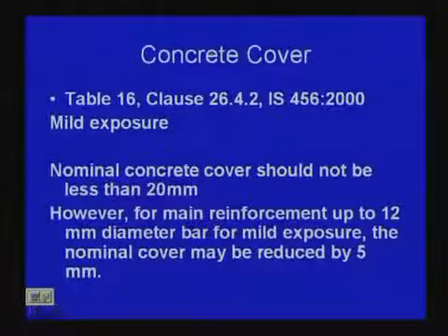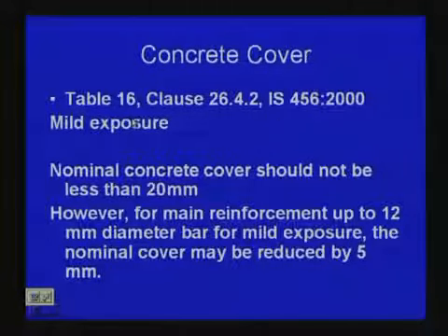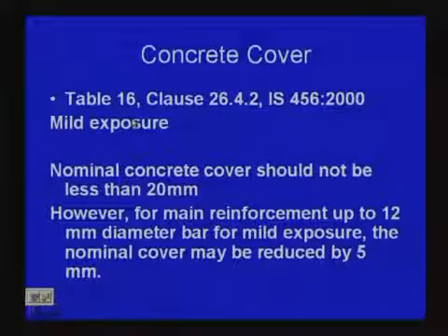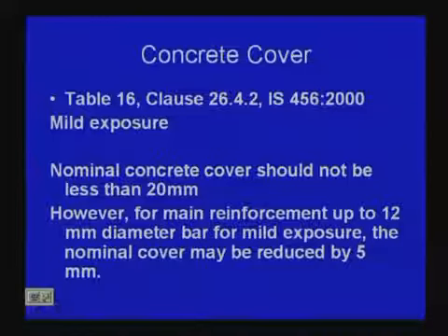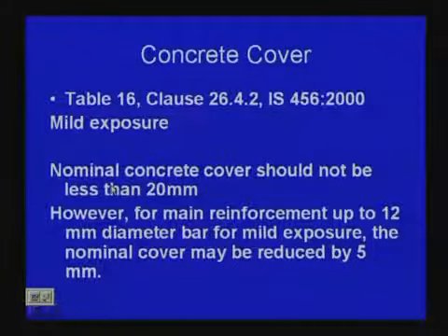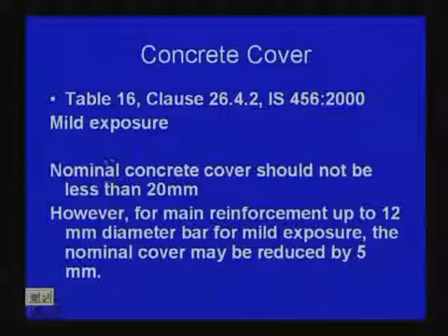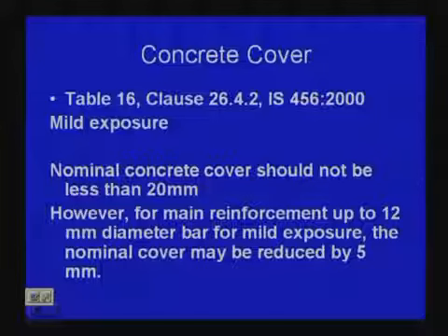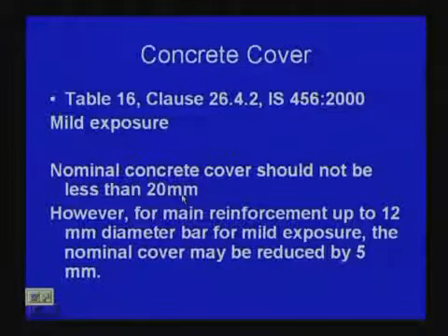What about the concrete cover? You will find that in table 16. We have already used a clear cover of 25 millimeter for beam. So, you will find in table 16, clause 26.4.2 of IS 456 2000, and I have just given mild exposure, because there are so many other environmental exposures. So, nominal concrete cover should not be less than 20 millimeter.